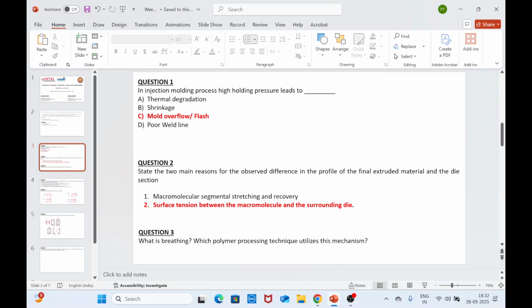In compression molding, you are going to compress the polymer melt. Every material will have certain air pockets. When you try to compress, all these air pockets that are present will try to collapse into each other, and because of this collapsing of small air pockets, a bigger void will be generated. This void generation is detrimental to the material, because voids tend to reduce its properties.